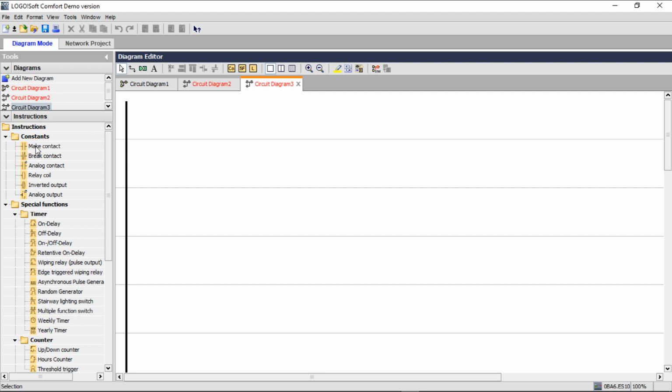They use simple addresses I1, I2, I3, I4, I5, I6 for inputs that are linked to your input module. For outputs, it's Q1, Q2, Q3, Q4, and so on. So let us make a simple program: when you press the start button, your green light comes on. When you press stop, it then goes off.